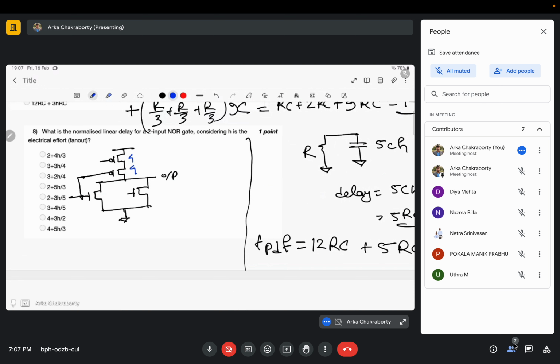Okay, and NMOSes, as they are parallelly connected, I don't need to change their values, because worst case would be R. So I will be keeping the W of NMOSes same as the unity inverter case. So it would be 1, it would be 1. Okay, so what will be the capacitances? The input capacitance would be 4C plus 1C, 5C.